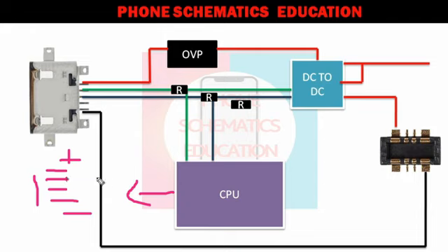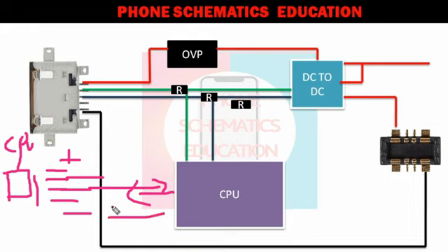When you connect through these data minus and data plus lines, your pen drive's MCU, or you can say the main IC, is connected to your master IC. After that, you can read or write data on your flash drive. I hope you get my point. In data mode, your phone will be charged in slow charging mode, most probably 0.6 ampere.